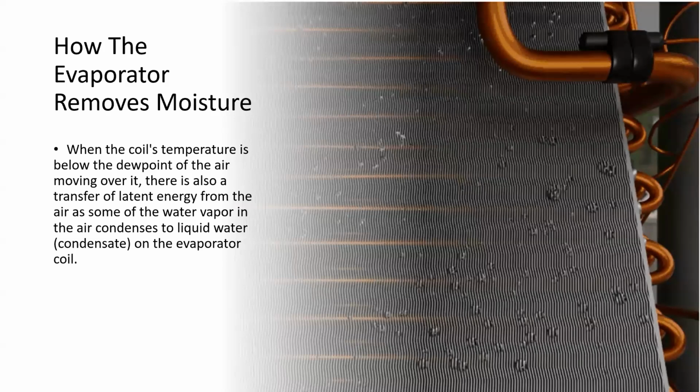The difference is when you have a system that is moving way more airflow. Let's say we take a 400 CFM per ton system in Phoenix, Arizona, and we try to put that somewhere coastal where we have some humidity on a hot day, and we are not removing that humidity. The sensible load in the home will go down, and your thermostat temperature will go down. But if we're moving too much air, we may not be able to remove that latent load. So the home will feel kind of cold and clammy, like a wet cave. It'll feel cold, but it's still going to feel humid.